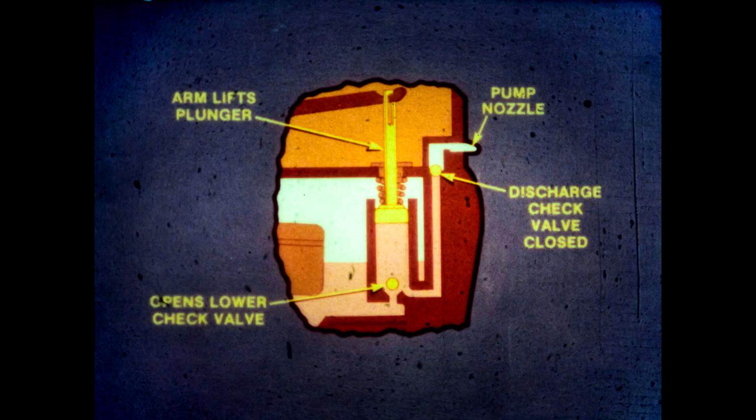Our next circuit is the accelerator pump. There are two types of accelerator pumps in use, the piston and the diaphragm type. When the throttle is opened suddenly to accelerate, airflow instantly increases through the venturi, but there's a brief time lag before fuel can overcome its own inertia and start to flow. This momentarily leans the fuel-air mixture.